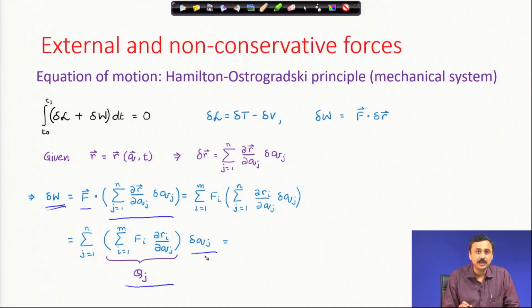If q happens to be a linear coordinate, a displacement coordinate, then this is force, but if q j is an angular coordinate, remember this capital Q j must be a moment. Because capital Q j can be force or moment, these are called generalized forces. The product of generalized force and the corresponding variational displacement is work, so it must have dimensions of work.